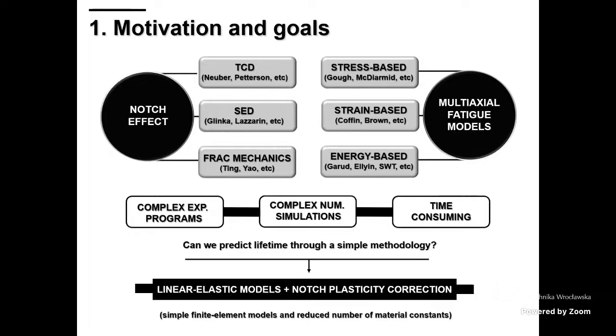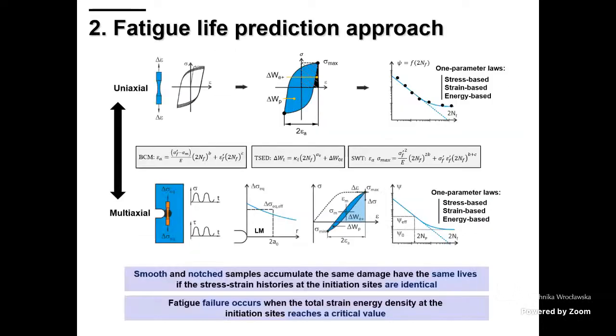So the idea is, can we estimate the fatigue lifetime under multi-axial loading using simple methodologies? So I'm going to answer this question. Our idea is to explore the possibility of using simple linear elastic models combined with notch plasticity correction. So the proposed methodology is summarized here.